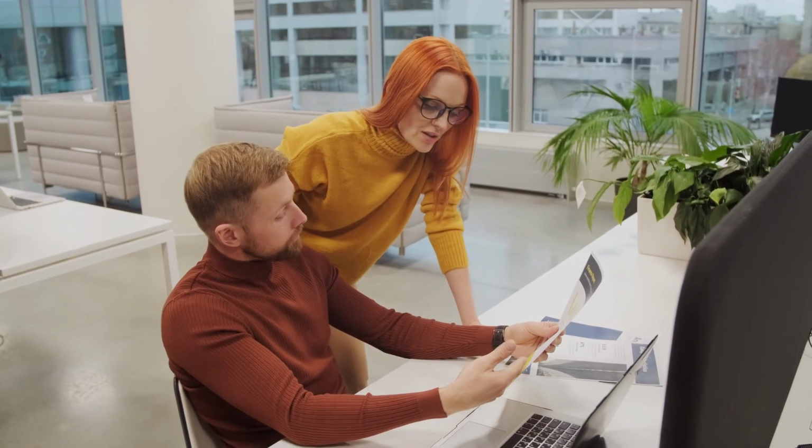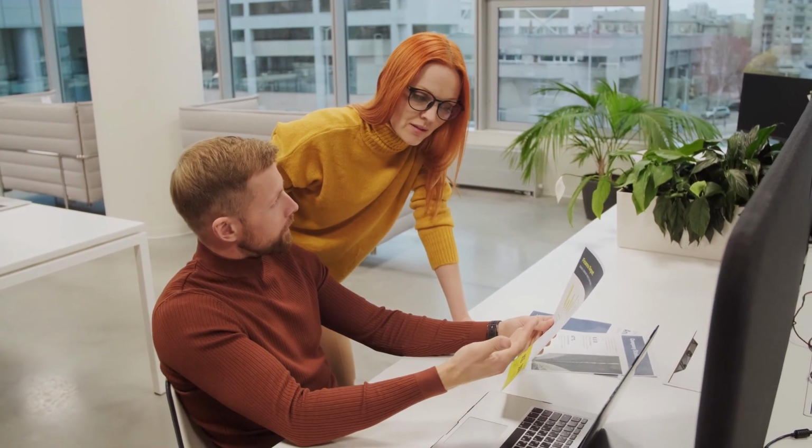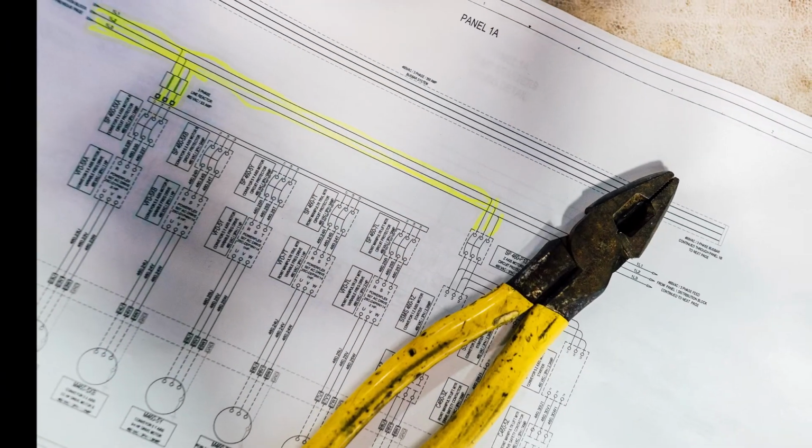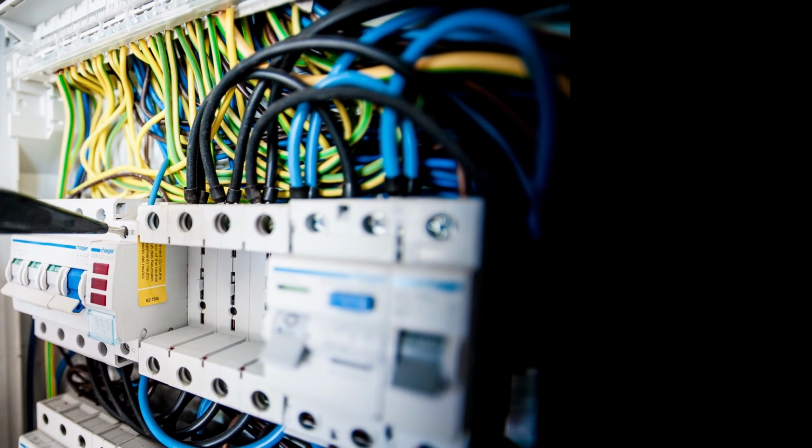Redo your calculations and check against the existing brake resistor. If you find that your brake resistor can match the drive, then you're good to go. Otherwise, you'll need to upgrade. Well, that wraps up our quick tour of dynamic brakes.